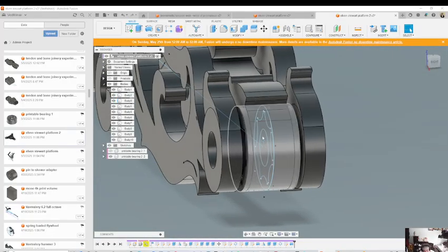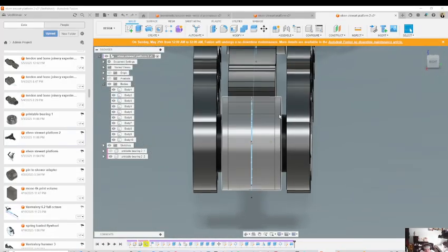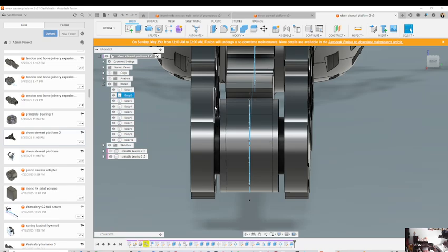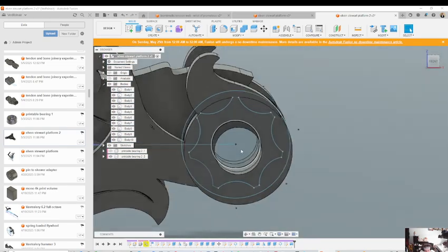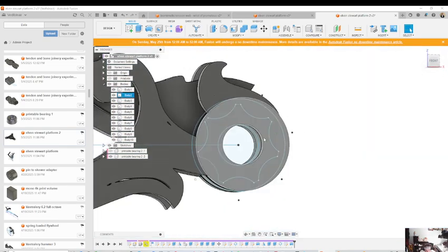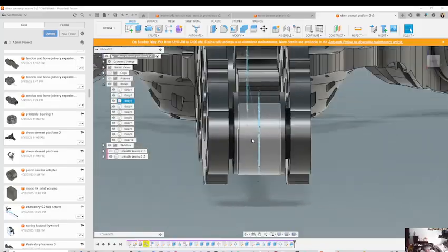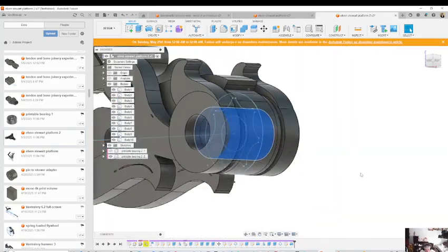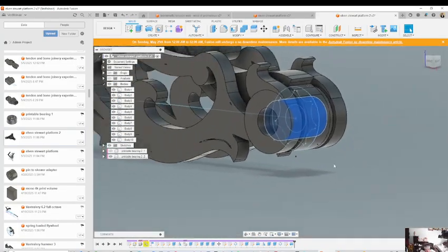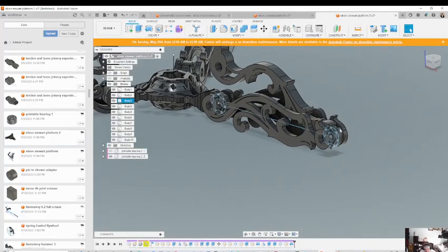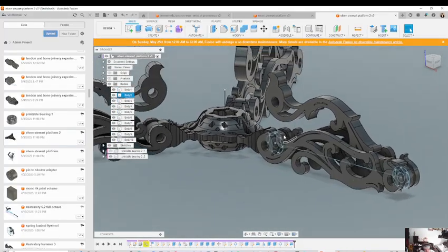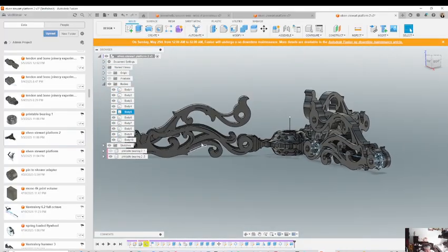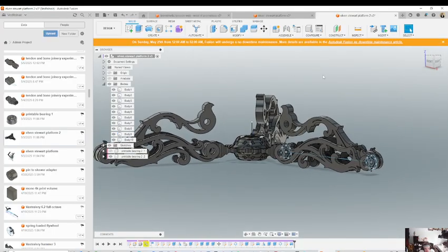So when I export it, it simply integrates. You can see the clearance here is 0.5 on each side, and there's the axle going through, and the geometry is nice and stable and effective. So the axle is right here. That joint is simply printable, so you can print it and it spins, which is kind of nice. And then you have this filigree pattern for the legs, which I thought was very interesting.